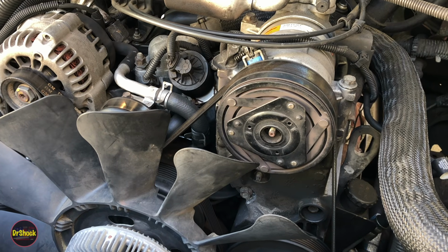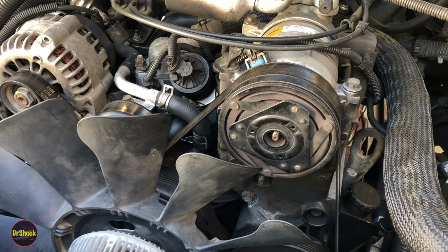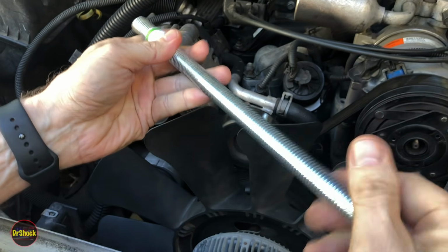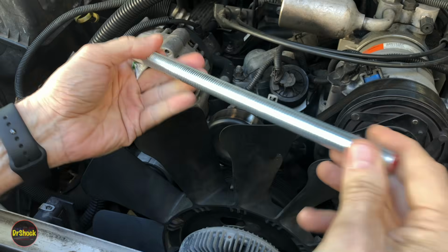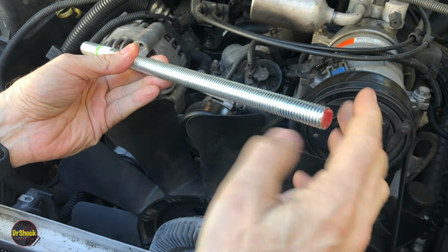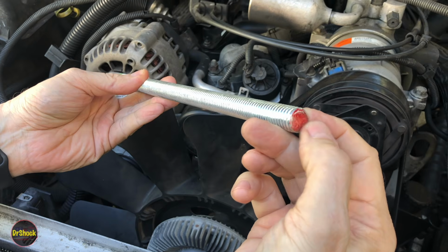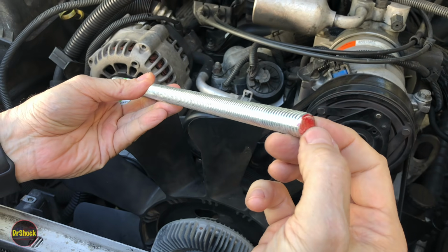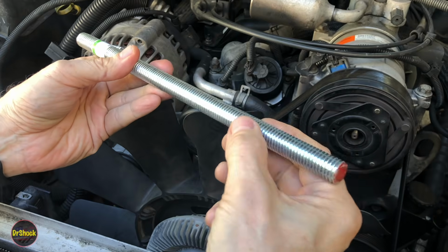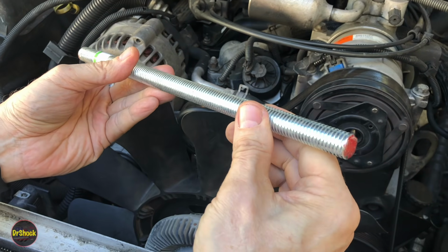So those two options are either you can take some 5/8 by 11 threaded rod like this, because that's the thread that the forcing nut needs. And you can cut this to length, then sand off the end, center punch it, drill it, and tap it for M8 by 1.25, and we could get it on there, and you could put a couple of jam nuts on it, or you could weld a nut on it.